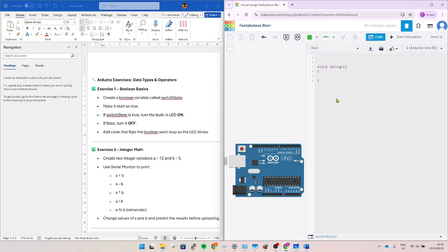A key characteristic of a variable is where it can be modified from. If I put this in the void setup, will I be able to access it from the void loop? No, you won't. Let me turn to the page and get the proper name for it. It's called scope. The scope of the variable is now limited to void setup. So we would actually put this here